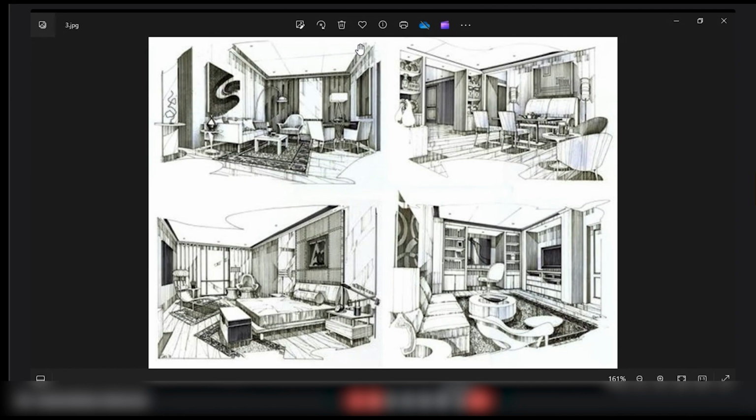And bold strokes, when applied with increased pressure on your drafting sheet, bring clarity and definition to your final sketch. Correct. So when you start drafting, you use lighter shades and lighter strokes on your drawing, and once you are satisfied with your combination and your composition on that 2D paper, then you start using bolder strokes to give the drawing exact clarity and definition in the final sketch, correct?